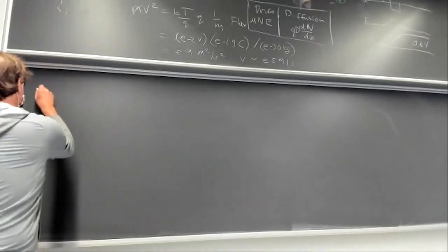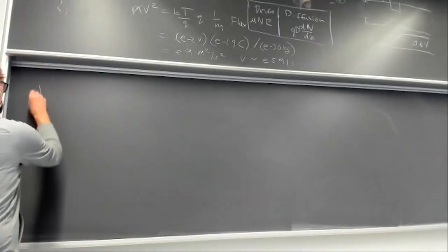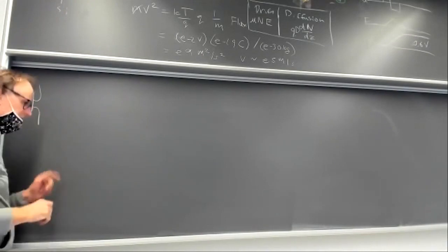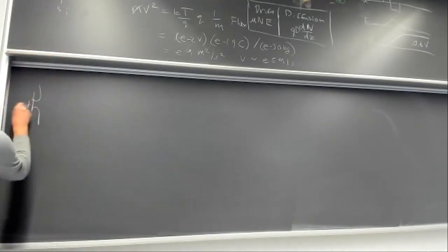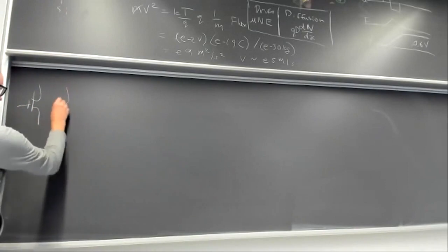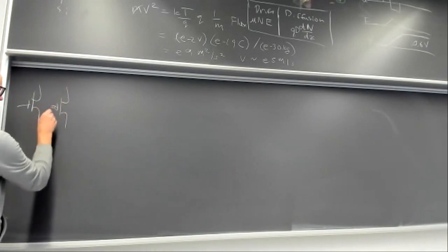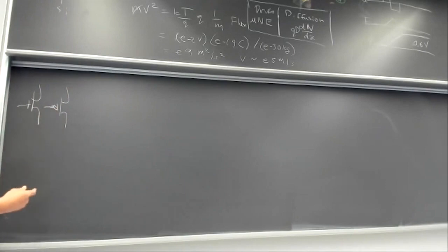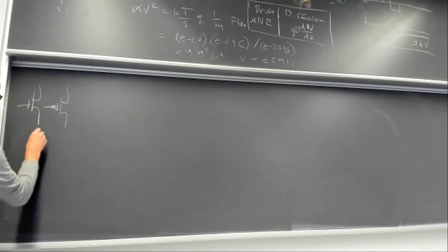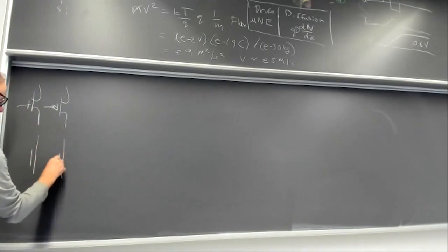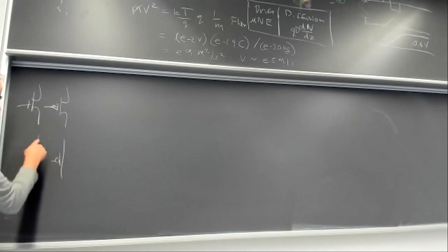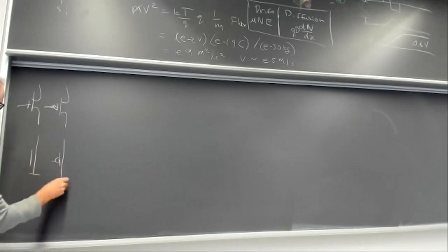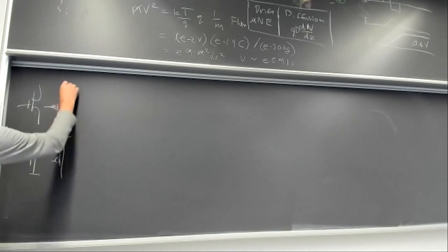So we're just going to write the transistor symbol. Then I'll talk about the PFET later. There's many ways to draw this transistor symbol too. Like this is an NFET. And this is the PFET symbol. There's a bubble here. That means it's a PFET, because it carries holes instead of electrons. I personally like Andre DeHon's style, where you just draw like this. You don't even bother with the squiggles, it's faster. This means ground, and this means VDD, power supply.